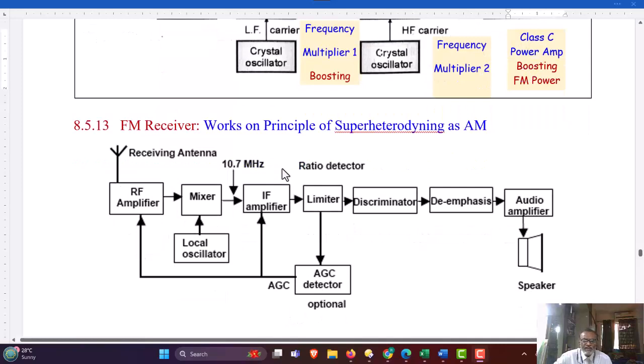Now when this FM signal is radiated, it will be received by various receivers. So let us see how the receiving system, called the FM receiver, works. Here the antenna will catch the signal which is transmitted by the transmitter. The signal from the antenna is very weak, so it first needs to be amplified. The amplitude of the signal will be increased by using an RF amplifier. The RF amplifier additionally provides a selectivity function.